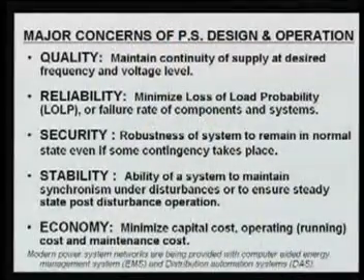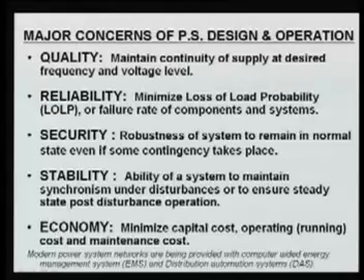Normally people get confused between reliability and security. Security is related to the robustness of the system to remain in the normal state. What is the normal state? It means your operating limits of the power system, that is, line flow limits, voltage limits, generator limits, tap limits, etc. If all are well within limits, we can say our power system is secure. So if right now your system is operating in a well secure manner, in the normal state, there is no violation of the power system limits.